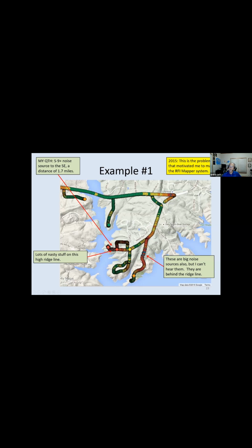And kind of interesting also, there were some noise sources on another ridge line behind the road we drove, but those never have bothered me because they're behind the top of a ridge, in dirt, such a good attenuator, they've never been an issue. So knowing the elevation and also the direction and the intensity, all those factors pretty clearly pointed out where I needed to be looking. And at this time I didn't have an ultrasonic detector, but my power line guy did. He went out and he didn't have any problem finding it.